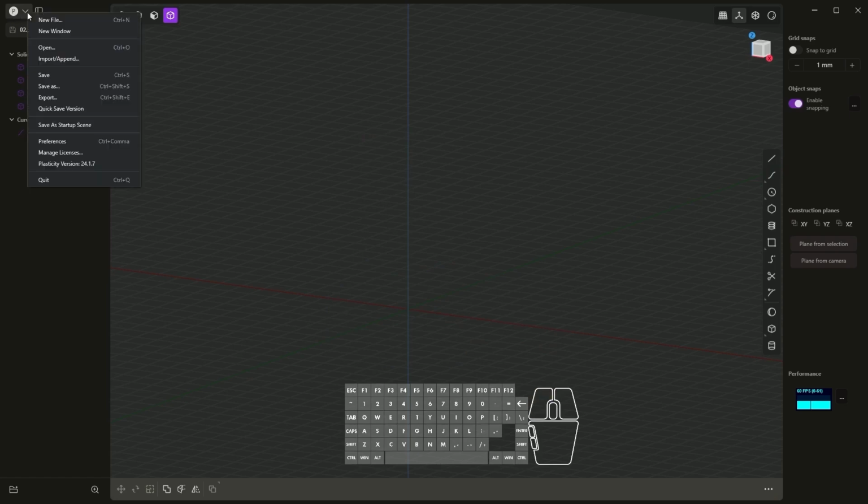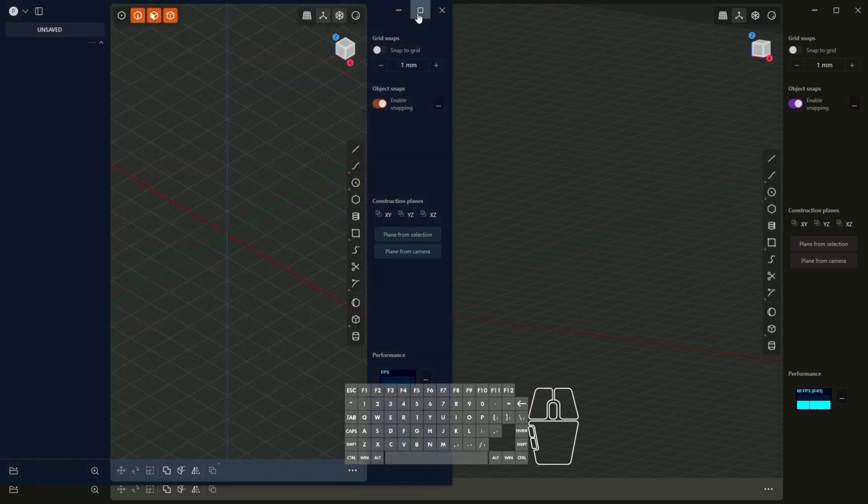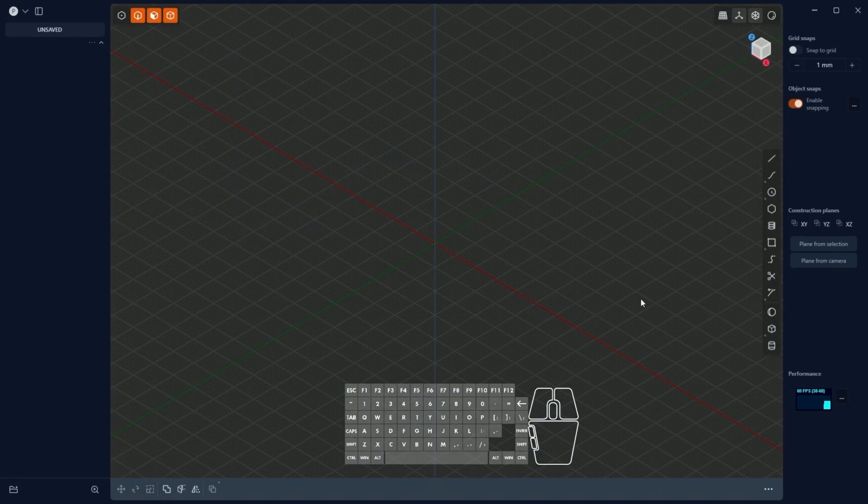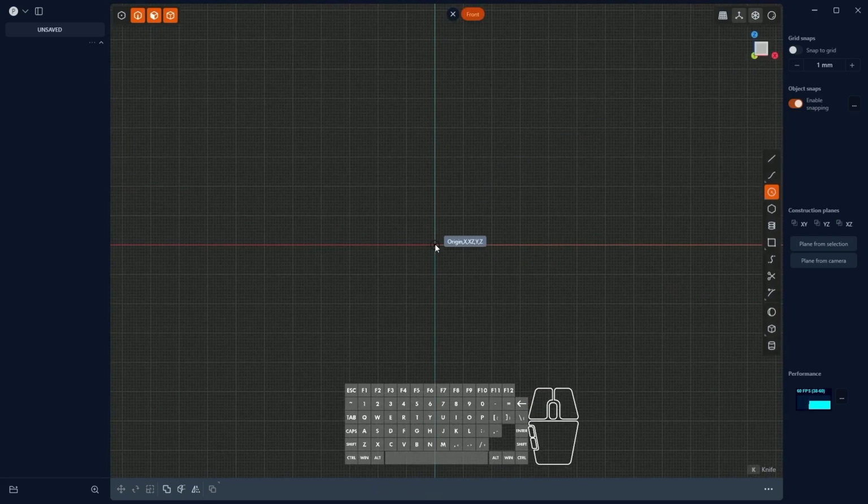I will create a new project and we will start by creating a cylinder. We could use this command, but we will simply add an extrusion of a circle and create a circle on the XZ plane. Select the circle drawing and start drawing the circle at the origin of the coordinate system. However, to ensure that the circle is drawn in the XZ plane and not in the XY plane, click here to attach to this view and left click at the origin of the coordinate system.